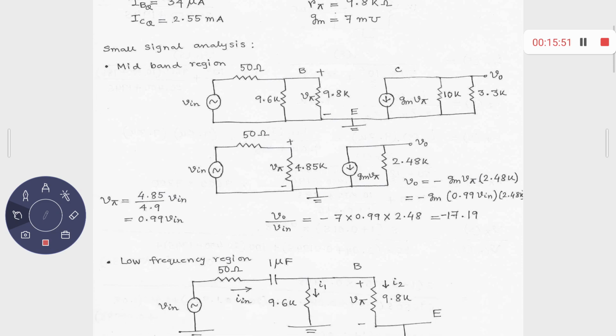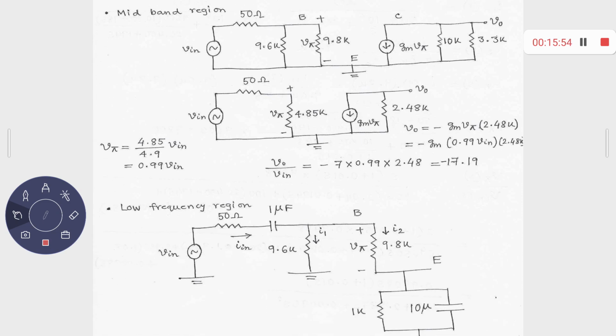Okay. So far so good. So up to this it is easy. There is no capacitor. Now the tricky part is coming. Now we are observing the low frequency region. If the frequency of operation is even less, as of now we have considered 100 kilohertz, right? Now even less, in the range of say tens of hertz or hundreds of hertz, then obviously you can get rid of the C pi and C mu because that impedance is even more, because it is 1 upon 2 pi F C. F is reducing, so obviously that impedance is even more, so you can just forget about C pi and C mu. But what about these capacitors, the CC and CL and CE, that you cannot neglect right now because now the frequency is less. These capacitors are in the range of microfarad, so now you have to take those capacitors into account, right?